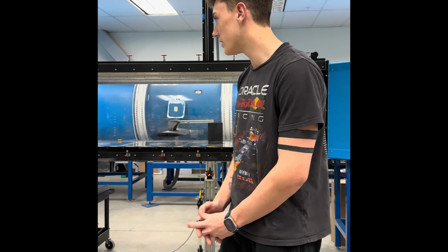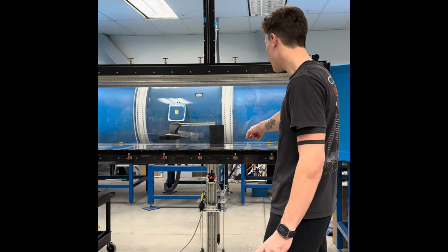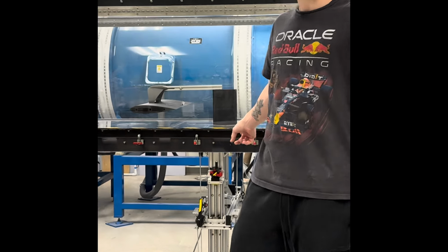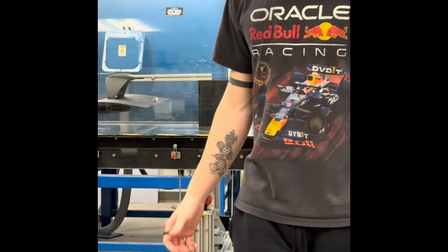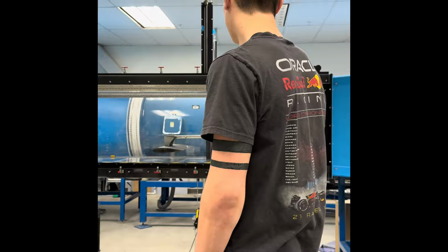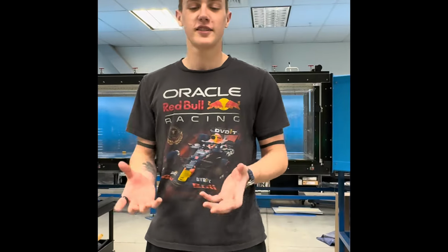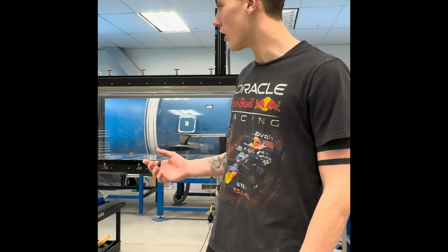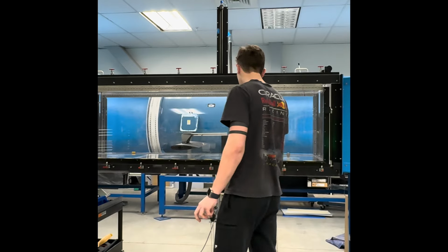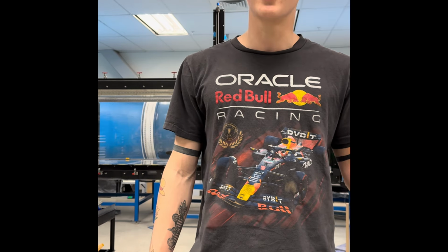Okay, with the wind tunnel, because we're going to be measuring multiple variables, it requires some calibration. We're going to be calibrating the load cell and the drag force measurement to make sure we have our known calibrated amount of drag force. And because we're calibrating it, we'll know our errors, and because we know our errors, that applies to the class because we can propagate all our errors and figure out a total error. There aren't any gaps because this is used a lot and it's well set up.